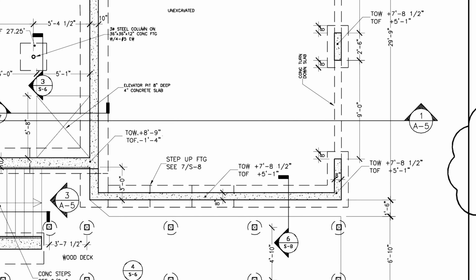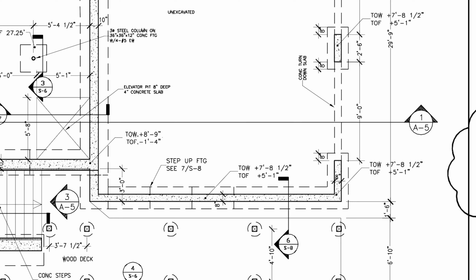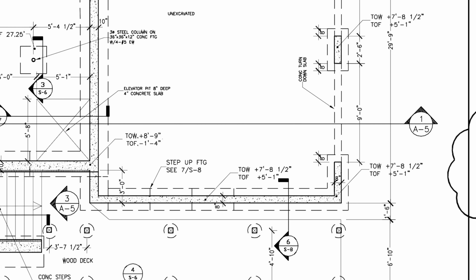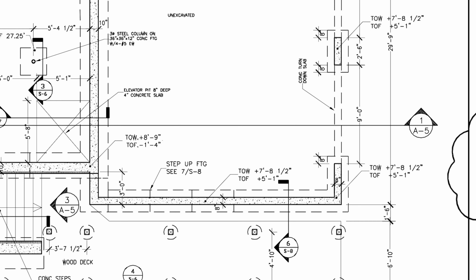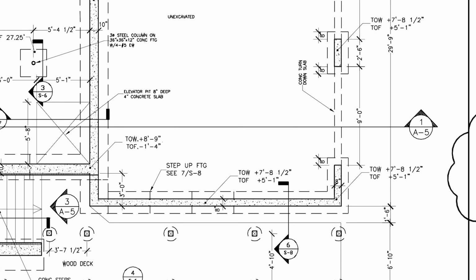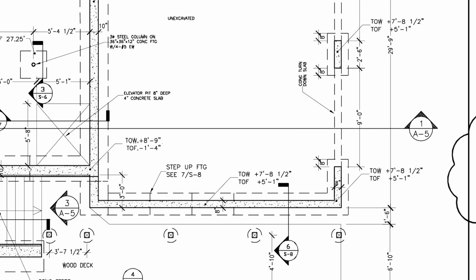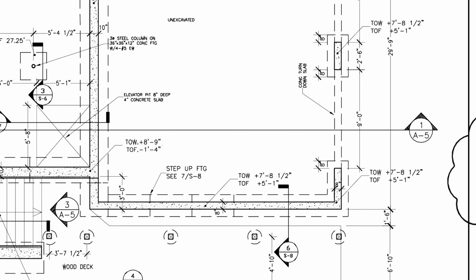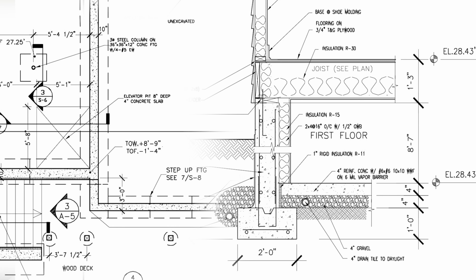So when we started to do an addition, we first started from footings. The dotted line represents the width of the footing, and then the solid line represents the concrete foundation wall, what goes on top of the footing. And if you remember going back to the wall section, this was the footing and this is the wall. And again, it has all the dimensions necessary.